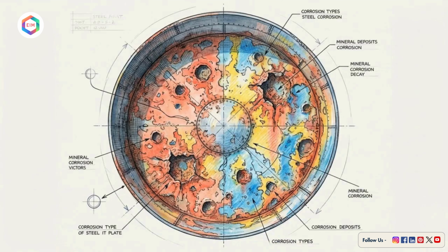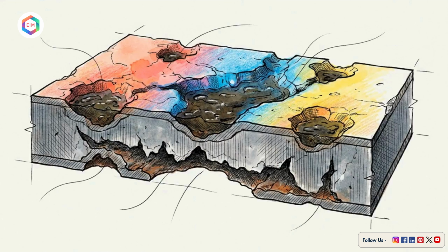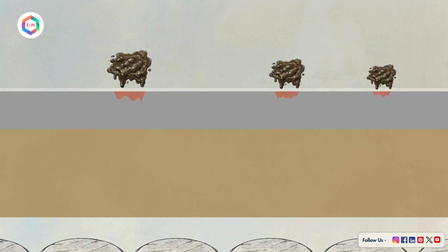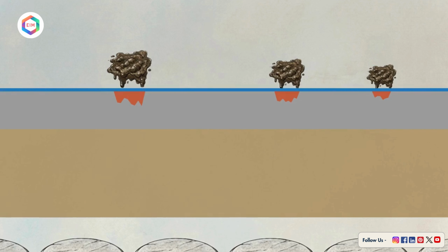The vulnerabilities at the bottom go beyond structural stress. The bottom plate is simultaneously attacked by 2 independent corrosion systems operating on opposite sides of the steel. Product side corrosion is driven by sludge and water settling on the floor. This top-down pitting is managed through internal inspections, water draw-offs, and linings. Soil side corrosion attacks from the foundation up. It remains completely invisible from the outside of the tank until the plate is fully perforated.